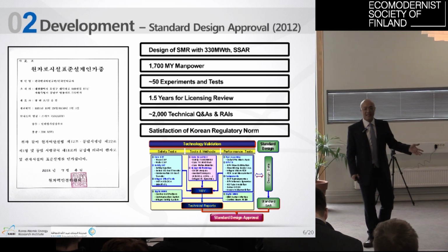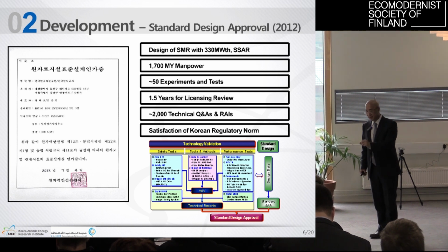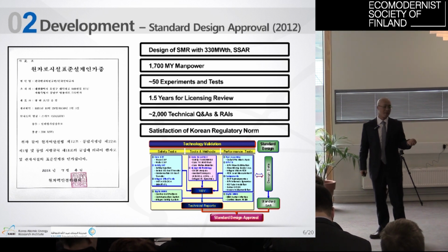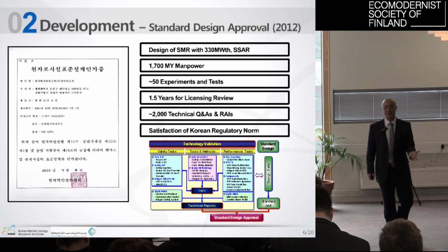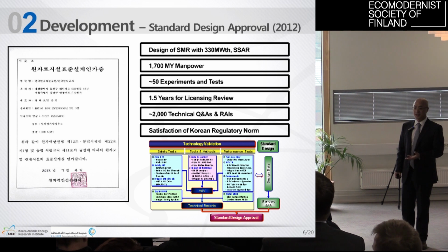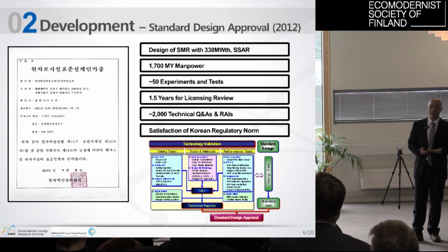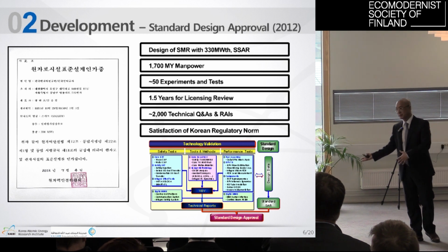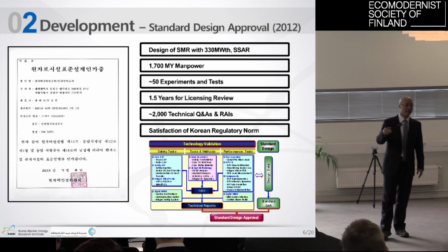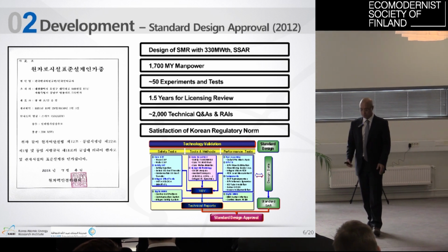In the SDA design, only the passive residual heat removal system was passive. Other safety systems, such as the safety injection system and containment cooling system, were active systems. So after the SDA, we changed all safety systems to passive. The current SMART design adopts the fully passive safety system.